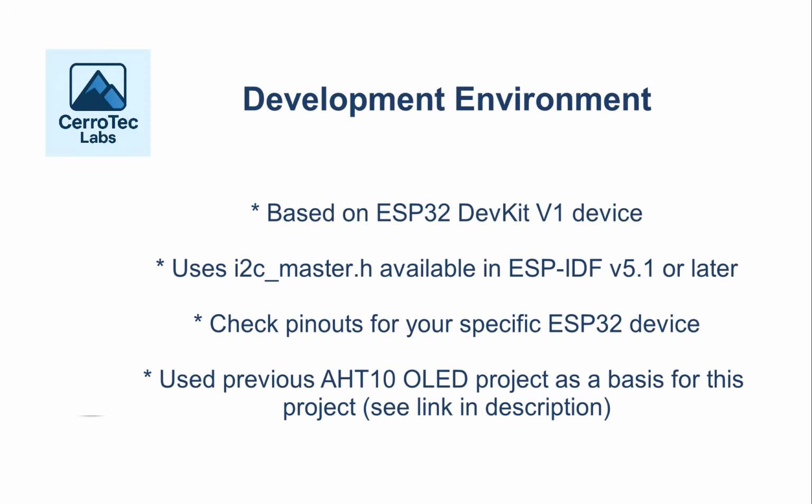A word about my development environment. I have developed this using an ESP32 DevKit V1 module. Please check your pinouts if you're using a different ESP32 variant. Note also that the solution presented in this video will only work with ESP-IDF version 5.1 or later. I have based this project on the code of a previous project. There is a link to that project in the description.